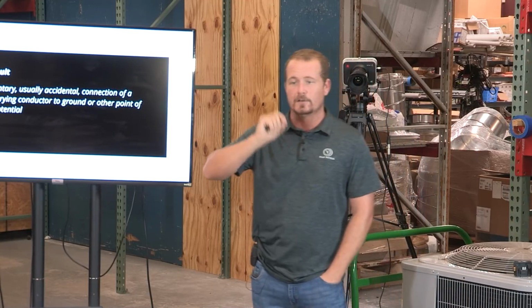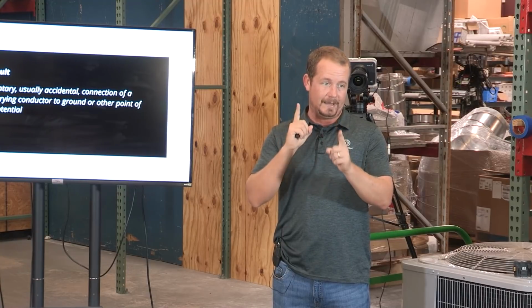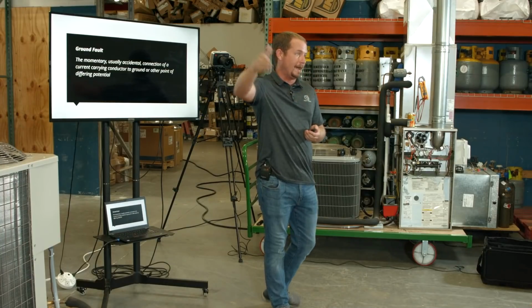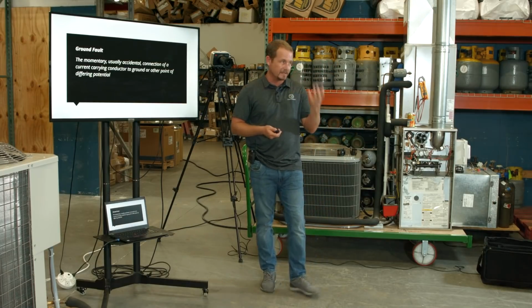Those are specifically designed to look for imbalances on the two legs. If there's an imbalance in current, that means that some of that current is leaking to ground, to some other path. And that can be unsafe. So we have insulation breakdown and all that.